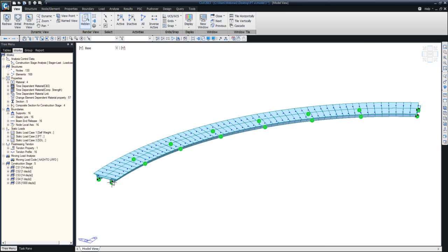So that member is very essential. If dummy elements or the transverse member is not in place, then there is no way that one girder line is sharing load with the other girder line, unless you make this as a finite element model with the webs and deck slab, everything with plate elements.